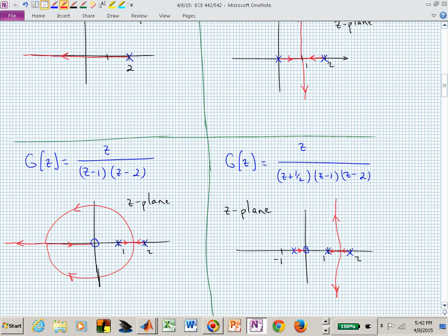We go over to the right, how many real axis line segments are there, or how many sections or pieces of this French loaf have we separated or identified? How many different pieces of that French bread do we have after they've been cut at the poles and zeros? 3 sections, don't we?